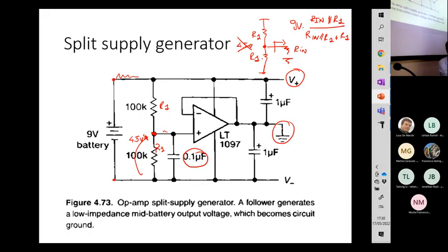I think the capacitance is, I mean that this voltage here should be provided to other circuits. Okay, so Rin is the input resistance of the other system. Okay, so if you plug directly the circuit that you want to drive at this point without this buffer, then you are affecting the voltage divider effects.